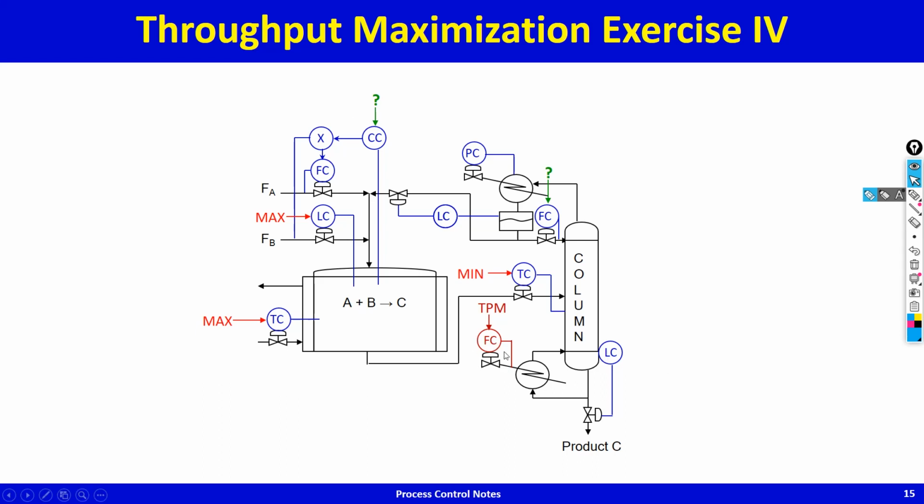The most interesting case is here when you're choosing the throughput manipulator at the bottleneck. In this case, what we will do is we will hold the delta P across the column by adjusting the steam to the column, and you adjust the steam to the column, boil up immediately changes. It's instantaneous or very fast open loop dynamics. So the control can be made very tight, and because the control can be made very tight, the variability in the boil up can be made very small.